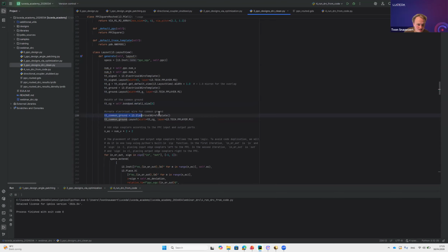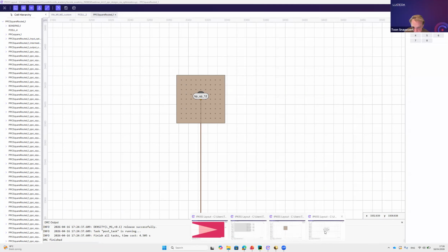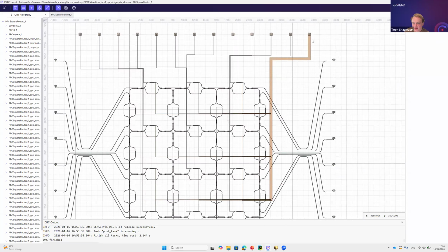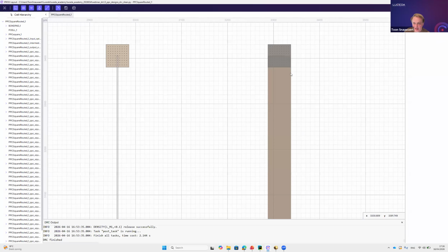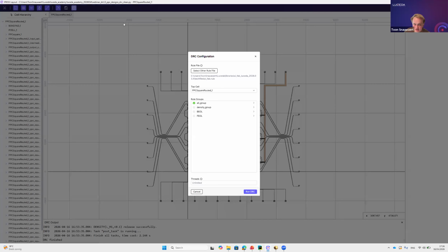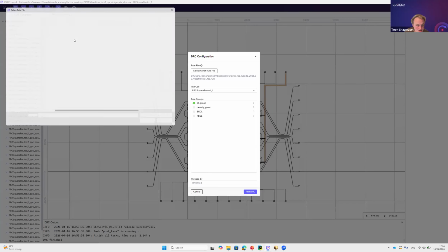Creating the wire, we need a trace template. So we create a wire template, and then we give it a certain width, which is the bond pad width, and the layer is, of course, our metal 1 layer. Afterwards, we get the following circuit, where we can see now that the metal layer has the same width as our bond pad. This should solve the last issue. Again, have a look.